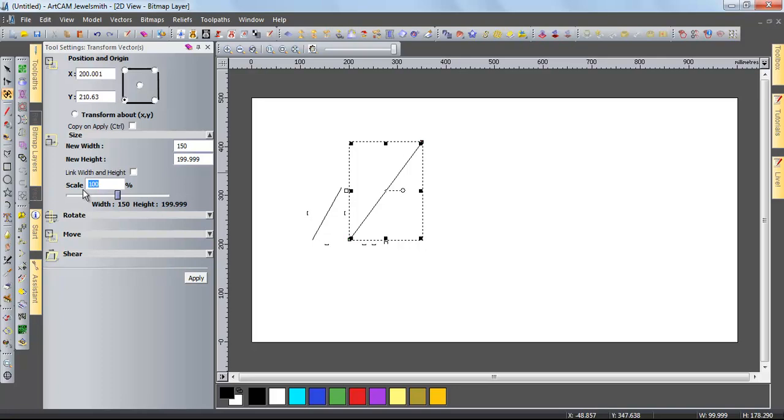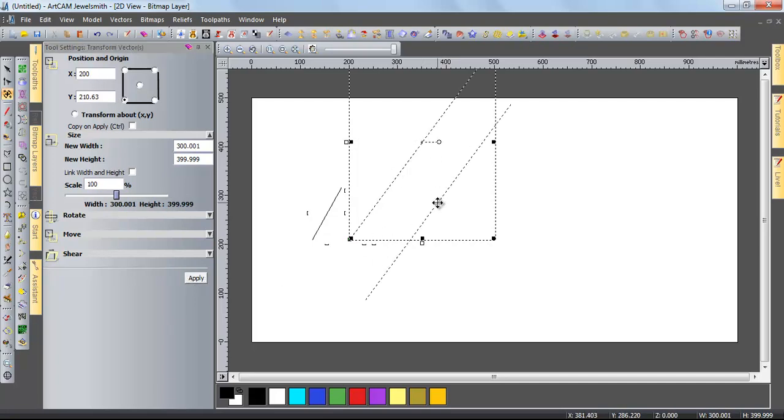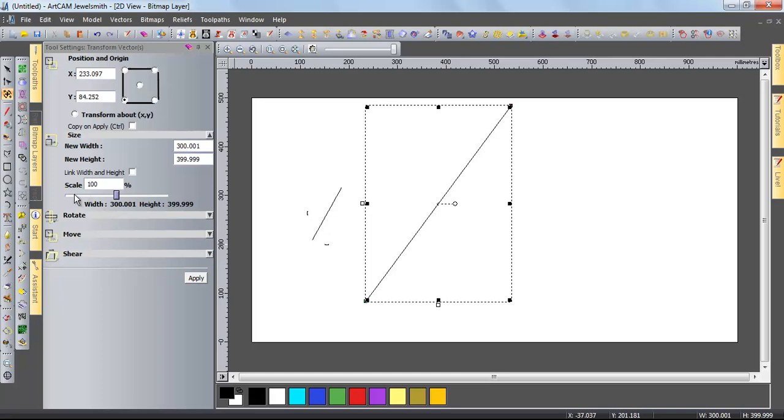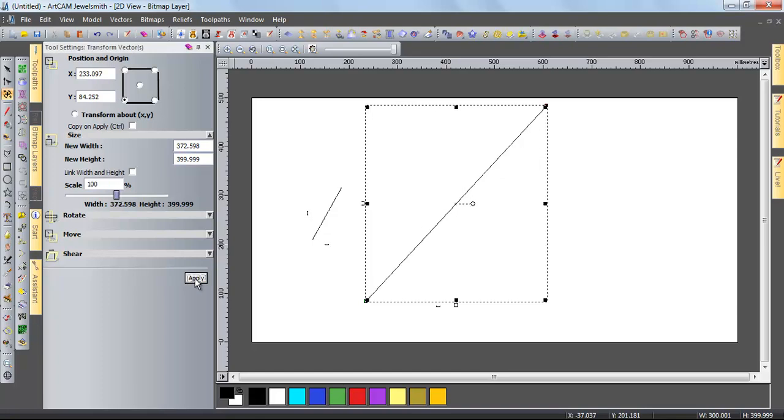In the lower part, the scale part, we can enlarge or reduce our shape. By entering the value here, that is, 100% means 1 to 1, the same size, we write 200% and we get a shape that is twice the size. Apart from this, we can operate by manually reducing or enlarging the size of this shape with the slider here. Apart from that, we said 24% and added it. We see the measure of its final state here too.